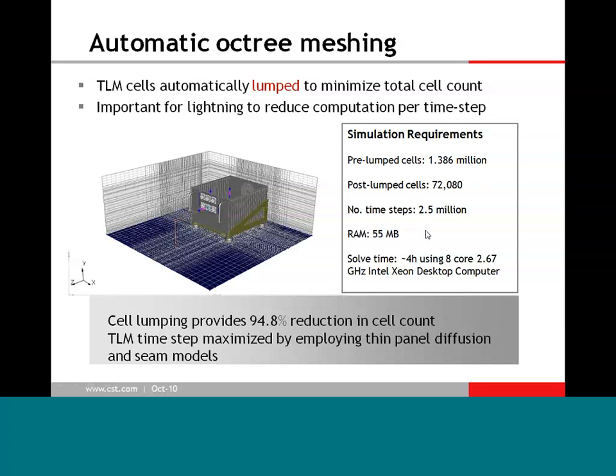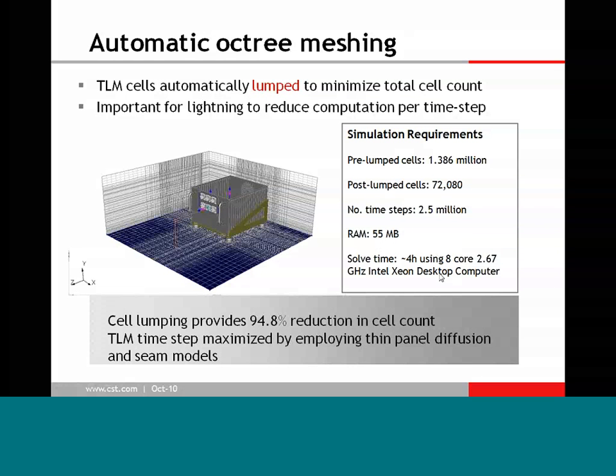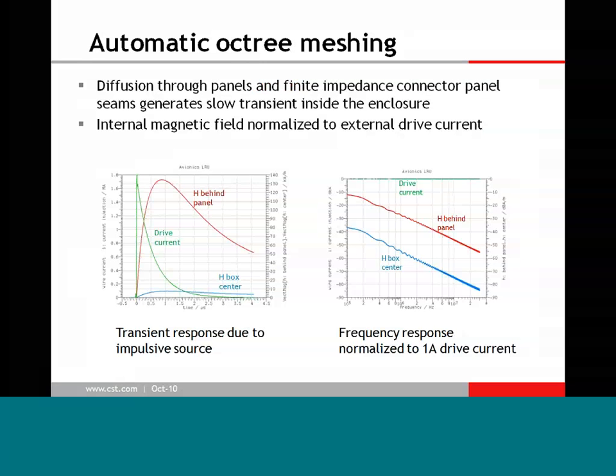So to cover the full lightning response, we would compute 2.5 million time steps for this problem. The memory required is actually very reasonable, 55 megabytes, and we can solve the enclosure in about 4 hours on a typical desktop computer. So the results would look something like this.